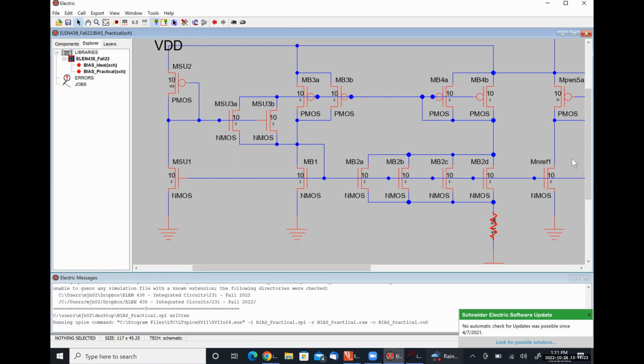If we press F5 right now, it's finding 13 errors, and I bet the overwhelming majority of those errors are extra pins. You'll go through and delete them, and I bet it'll look more like mine. That shouldn't mess with the behavior of anything, it just doesn't like nitpicky things. I guarantee that little stub of wire is an error, because it's a dangling wire.